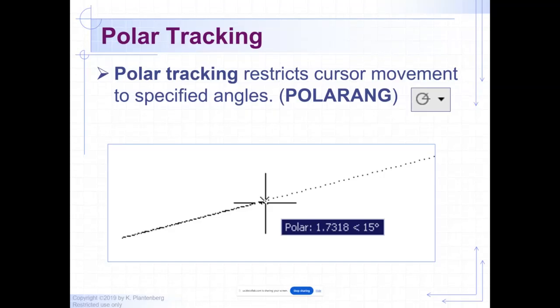A lot of your drawings in CAD and drafting are set up on 15-degree increments. It's either a 30, a 60, 75, 90, obviously 0, 45. Those angles are fairly typical. Well, if you set up your polar at 15 degrees, you've got it covered. You're good to go.